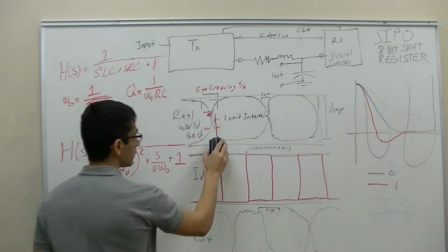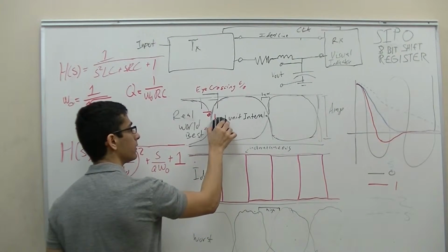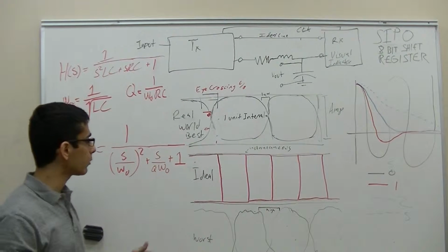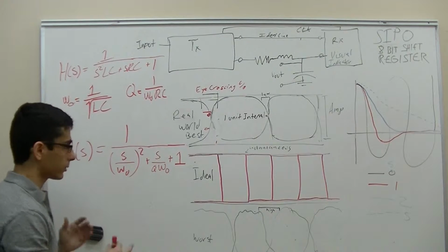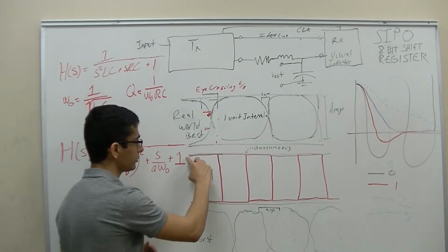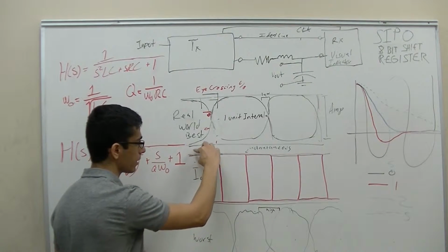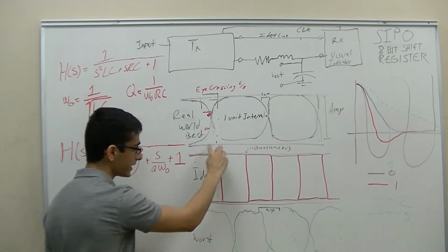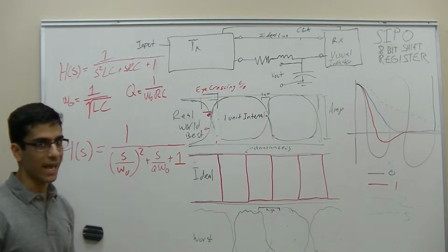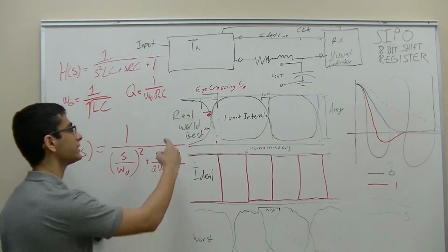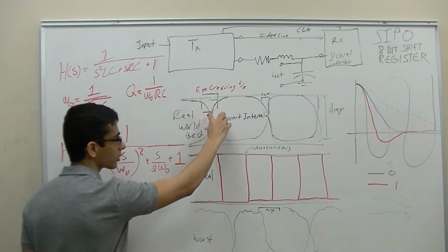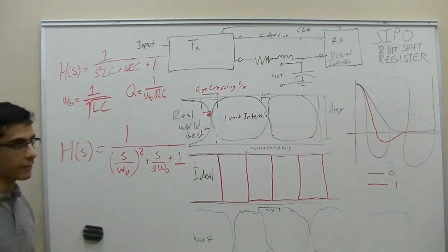Now we want to talk about the ideal case of an eye diagram, what we will see typically in the real world in a good scenario, and what we'll see in a really bad scenario. Ideally, you see that it transitions from a 1 bit to a 0 instantaneously. You don't see this in the real world because nothing happens instantaneously. What you'll typically see is something like this, where it takes an amount of time as it curves down to transition to a 0, or an off state.